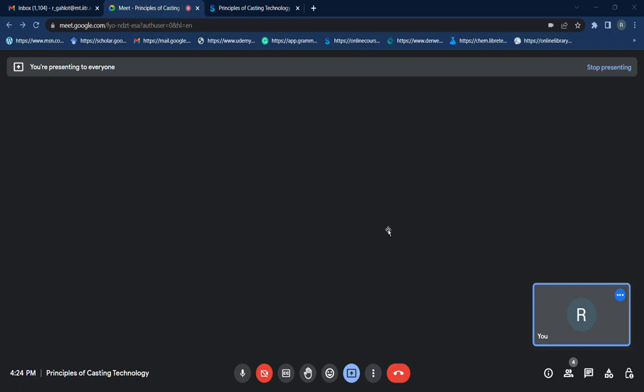So why does it enhance the corrosion resistance? The chromium stops oxidation. What happens is it forms a strong, stable oxide barrier layer and inhibits further corrosion. So due to that strong oxide barrier, it inhibits corrosion. Yes, a stable oxide barrier. So this will be the correct answer.